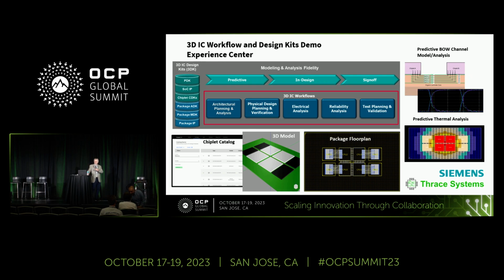Well, specifically when I talked about test here, it's for ATE testing. Right, and again, there are IEEE standards that support that. We strongly encourage that those are used. In the CDXML, we're basically providing a mechanism where the chiplet vendors can say, we're using this DFT method for this. And again, it's possible they can deliver the patterns and scripts in there if they choose to. More realistically, that'll probably be a relationship that they'll have directly with the end users. For functional verification, we have the Verilog models, so they could be used from that perspective for functional verification.